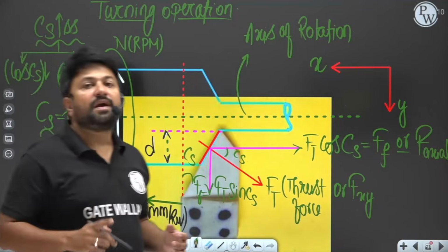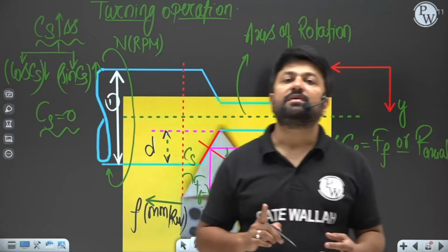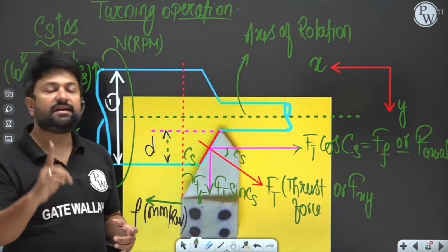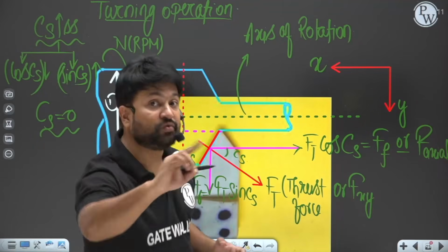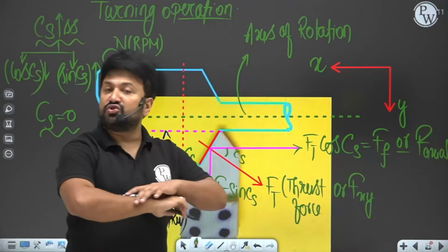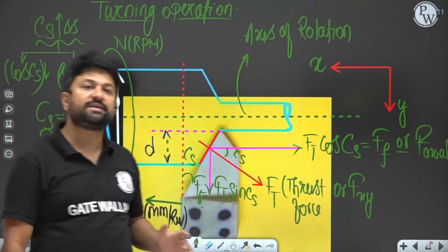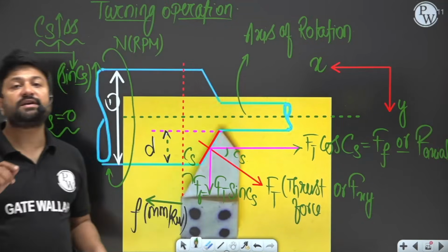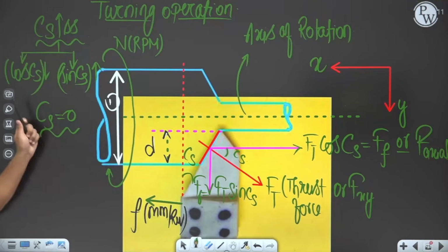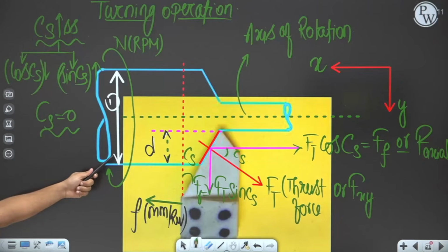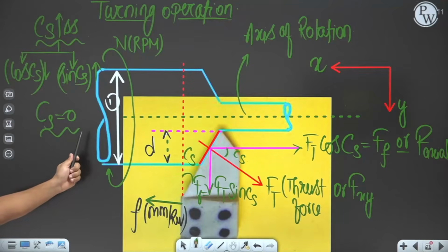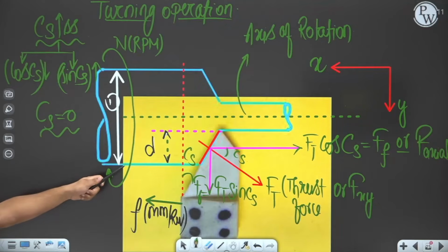Also, please remember, by increasing the side cutting edge angle, the cutting force and the power are not going to increase. This is a very important thing. By increasing the side cutting edge angle, your cutting power consumption or cutting force is not going to increase, right, my dear student? Now let's discuss some other extra points.